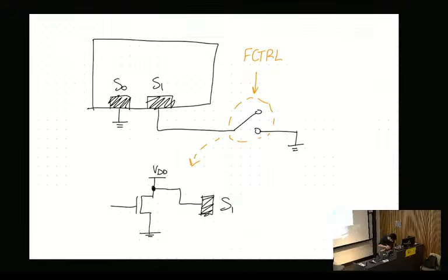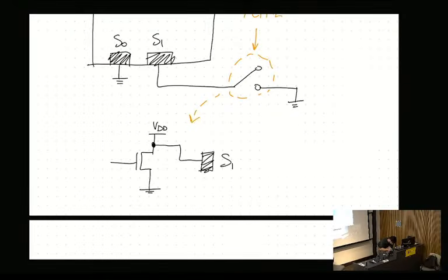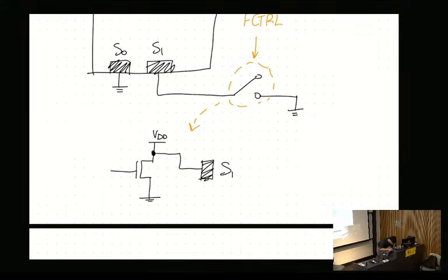It shouldn't look like that. It needs to be open for a clock frequency of 3 times, so when the signal is high, it should just be open. What did I do? I drew this incorrectly. What is incorrect about my drawing? Yes. So how should it be drawn instead, to make it so it's open? Exactly. So if anything, nothing there. I initially just drew it wrong because I'm so used to drawing a VDD, but effectively we just want to leave it open when the signal is high at the gate, and in the other option we want to be pulling it to ground.